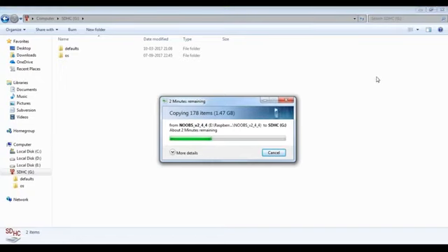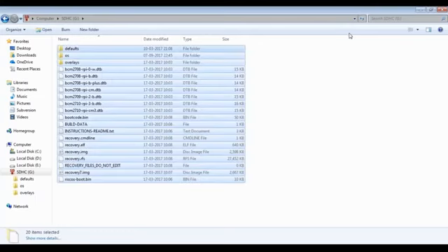Now once we're done copying, let's go on to install this memory card onto our Raspberry Pi and begin the installation process. So now we've successfully copied all that is needed for our operating system. Safely remove this, make sure you're ejecting it safely, because sometimes if you do not safely eject it, the files get corrupted before you load it into your Raspberry Pi. This is a certain issue with respect to memory cards.